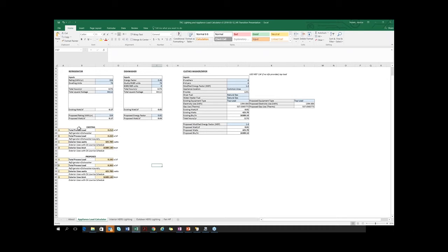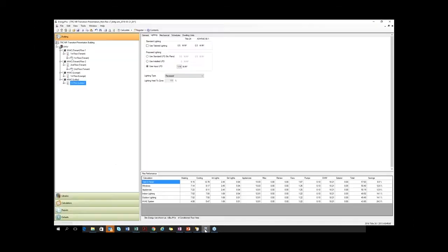laundry unit. So you're going to use the process load for inside the units just for the refrigerators and dishwashers, and that's right here. So it's 0.212 watts per square foot. So in this EnergyPro 7 model, you come into the room level, and where this is going to go is process sensible heat. So the way you update this is you could either come in here and say 0.212,